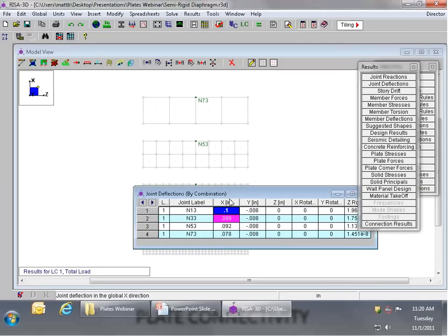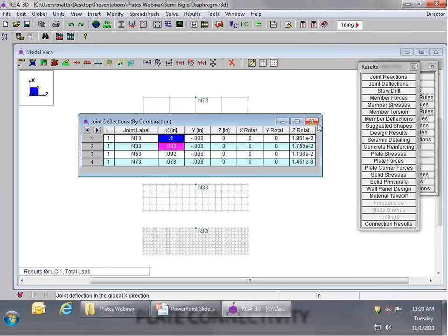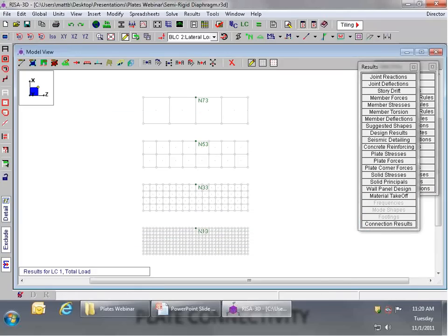Now at this point, we're talking about a matter of engineering judgment. If you had this model right here, and you submeshed it, and your results changed by 20%, it's easy to say, okay, I definitely needed to submesh that one. Now, when you go from this model to this one, you submesh, the results change by 6%. Some folks would say, well, that's less than 10%. It's not a big deal, I'll stick with it. It really depends on where you want to put your cutoff point.